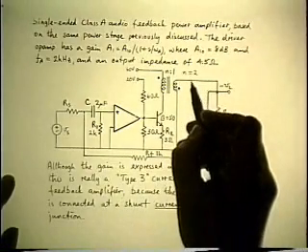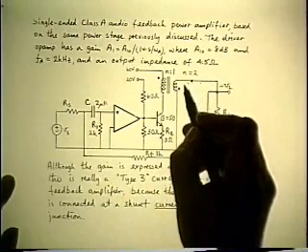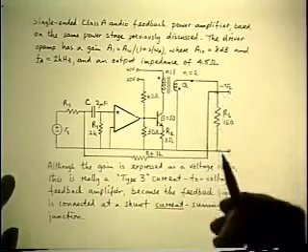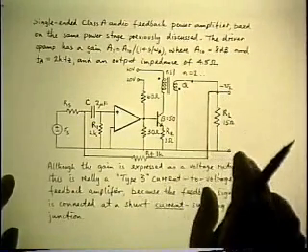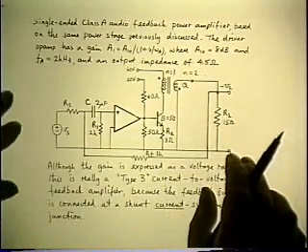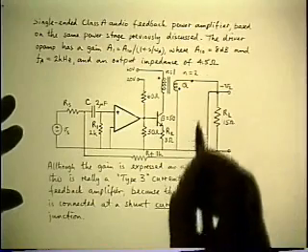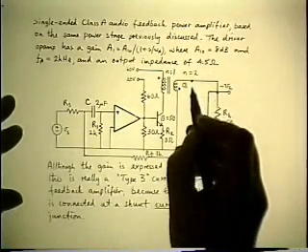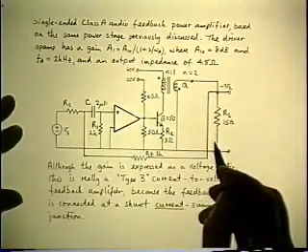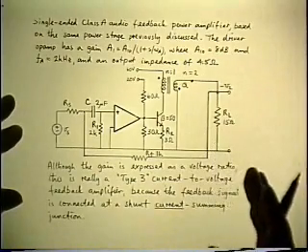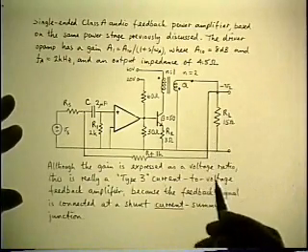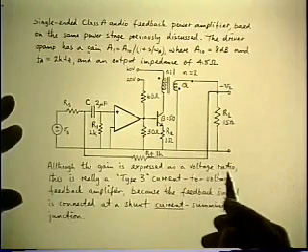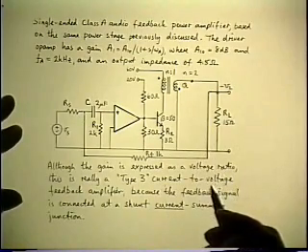So this was the point which was labeled Q. That's where we did shunt current injection on paper. So if we want to do this in practice on the bench as well, what we have to do is have a current source injected at that point. So the two things that we have to take care of in order to do that: one is we don't want to upset the DC bias conditions.